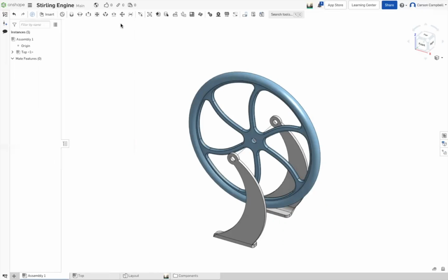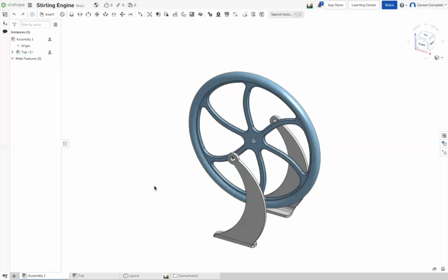All right, hold on. No fixes come. So the assembly is free to move around. I don't want it to move around. So pick one of the brackets and fix it. Pick one of the brackets. You can expand that, you can pick that, and you can say right, fix. All right. Try and move any of the brackets. Try and move the other bracket. How come the other bracket doesn't move? Is there a relation? Yeah, let's go over this. There is a relation. Most importantly, try and move the wheel. Okay, it's working.